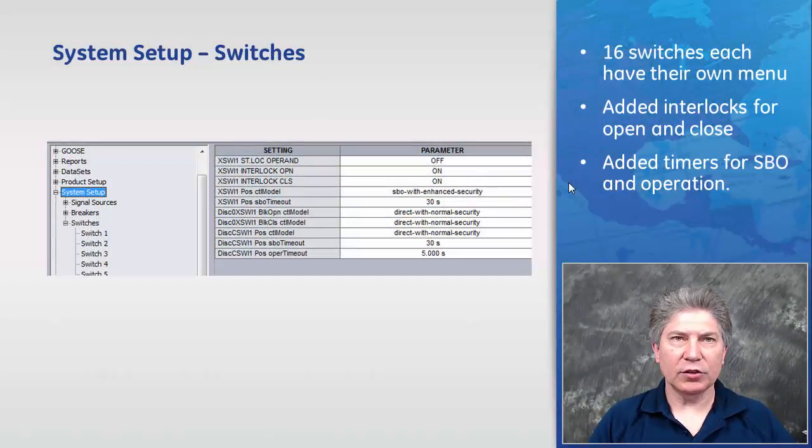Next, we'll look at the switches. Once again, we separated the 16 switches into their own menus, which made it much easier to read. We added interlocks for open and close operations controlled by flex logic operands. And we've also added security for control and added timers to select before operate, SBO, and operation timeouts.